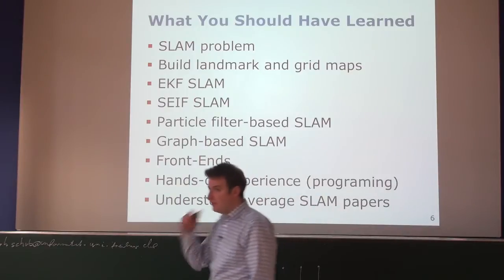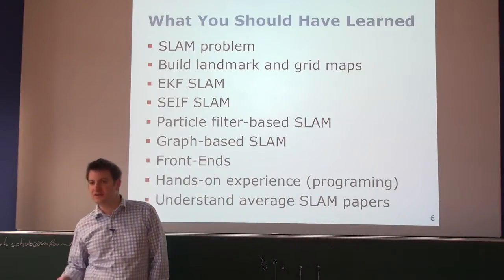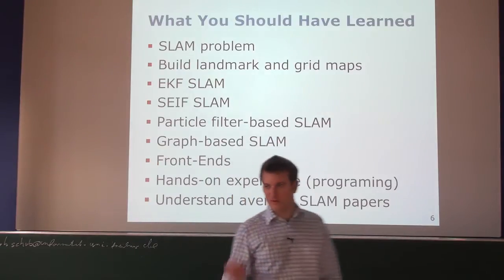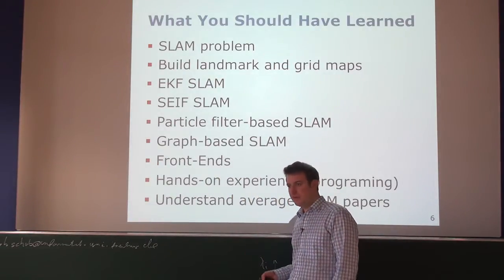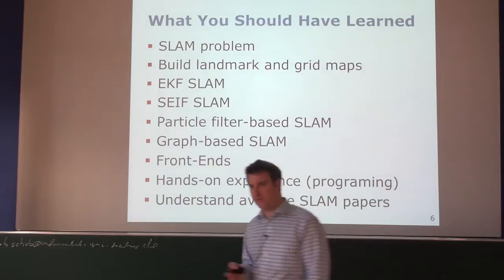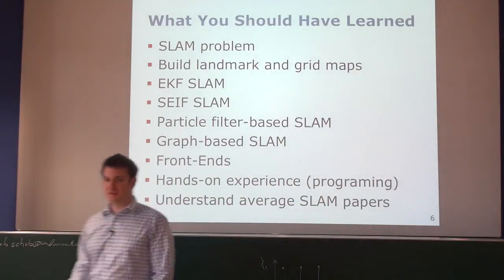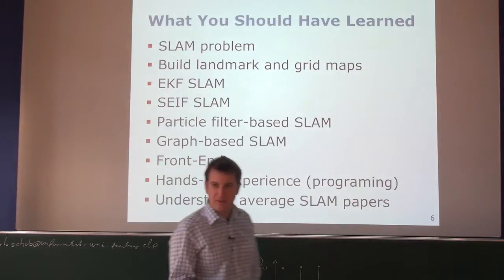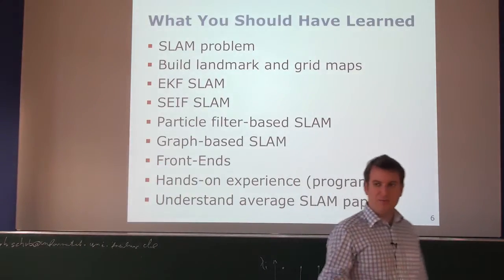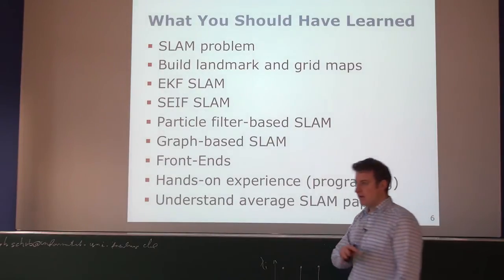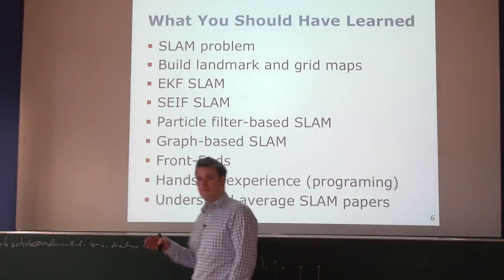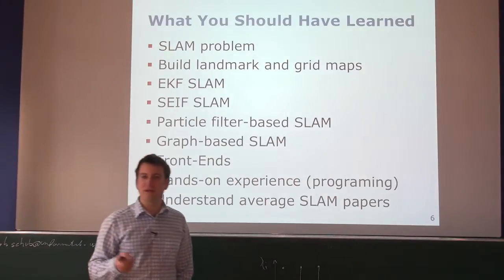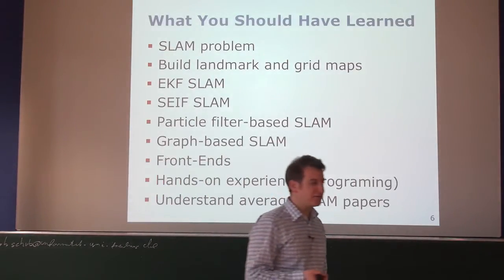You should get the idea of the particle filter in 3 key steps: drawing samples from the proposal, computing the weight, and the resampling step. You should be aware of these and know which things are exploited in order to apply that to the SLAM problem. What was the Rao-Blackwellization? How do we split up the estimate about the trajectory of the robot from the map of the environment in order to do that efficiently? That was the key ingredient to make the particle filter work in the context of SLAM.